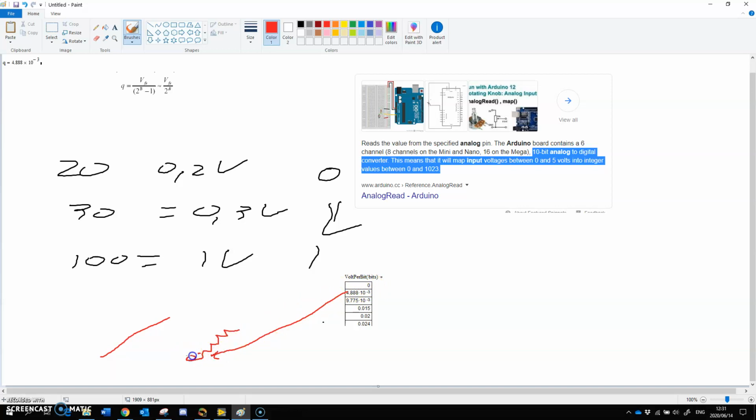But it means that this voltage is 0. This one is 4.883 millivolts. So we can calculate that back to temperature. If we're only going to go to 1 volt, we can see what temperature increase steps we can do. So we can't measure those in-between values. So you must make sure that the resolution you want to measure, the temperature steps that you want to measure, actually fits into these 1000 points. In this case, you only have 1000 points. So if you're going to go from 0 to 100, you only have 1000 points, but you only go to 5 volts.